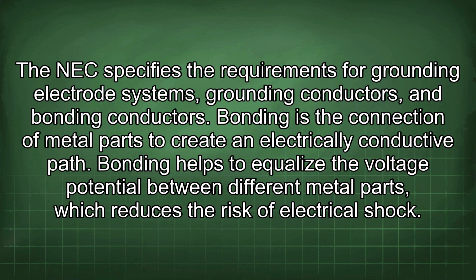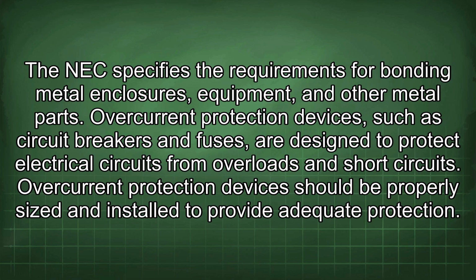Bonding is the connection of metal parts to create an electrically conductive path. Bonding helps to equalize the voltage potential between different metal parts, which reduces the risk of electrical shock. The NEC specifies the requirements for bonding metal enclosures, equipment, and other metal parts.